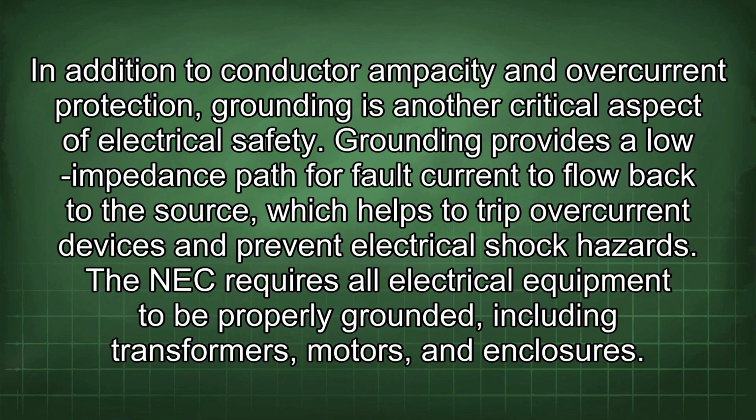In addition to conductor ampacity and overcurrent protection, grounding is another critical aspect of electrical safety. Grounding provides a low impedance path for fault current to flow back to the source, which helps to trip overcurrent devices and prevent electrical shock hazards.